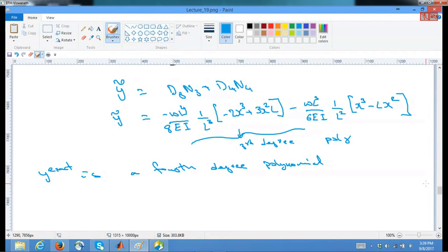But how to make sure that our FE solution gives something closer to the exact solution? That is achieved by increasing the number of elements. Let's say instead of a one element solution we go ahead and seek two element solutions, or four element solutions. That means we are fitting a piecewise third degree polynomial over the regime. What happens is this piecewise solution will have a closer approach.